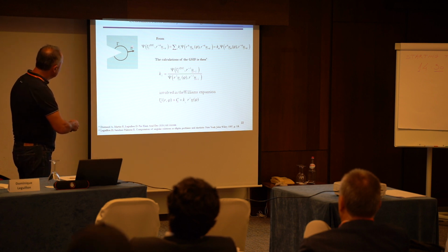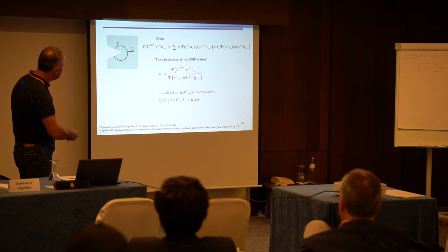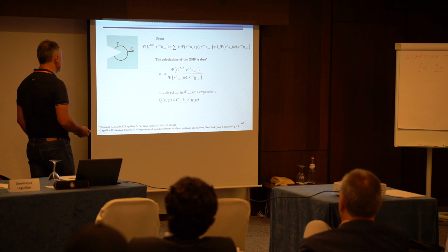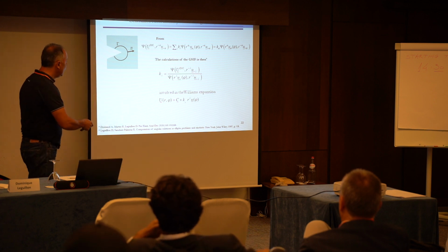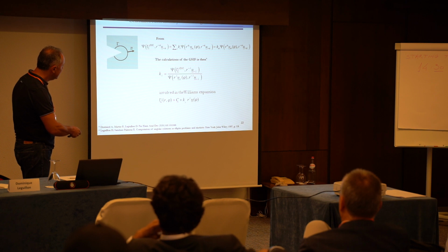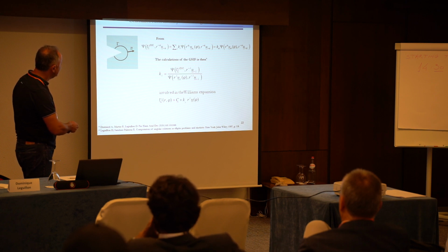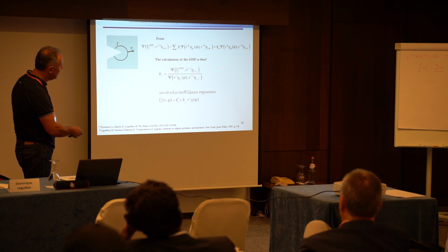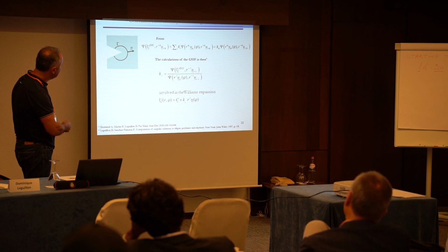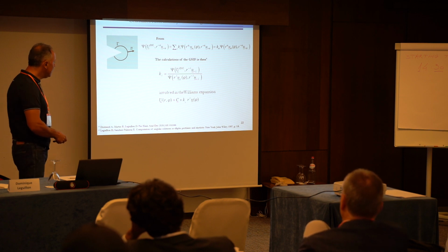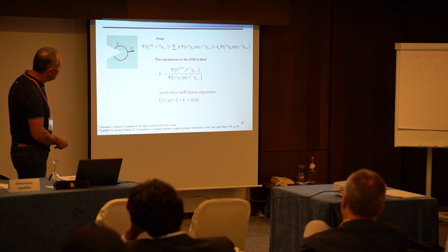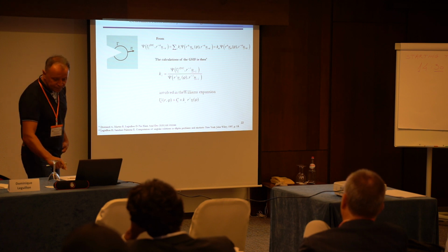Running these calculations across different paths allows you, from the calculation of capital C with the real displacement field and the reference solution, to extract the generalized stress intensity factor. So it is a matter of what? All of these things are known. This is measured. And you need to calculate, you have the displacement field, strain field, stress field, to calculate this capital C along different trajectories. And you come out with the truncated, generalized Williams expressions of this shape.